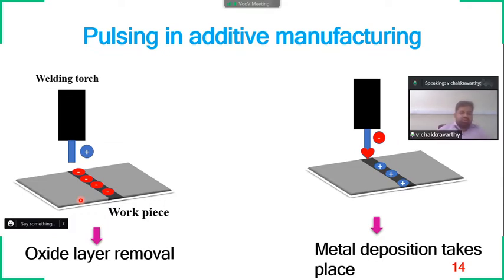Those kinds of costs can be overcome by wire arc additive manufacturing, because most wire arc additive manufactured components can be manufactured in an open environment. We provide argon as a shielding gas; argon, helium or varieties of shielding gases can be used. So we need not provide a closed environment for this. Only for certain materials which are very sensitive to oxide formation, only for those materials we may need to fabricate a closed chamber, I mean a closed glove box kind of environment. I will cover it in the upcoming slides.